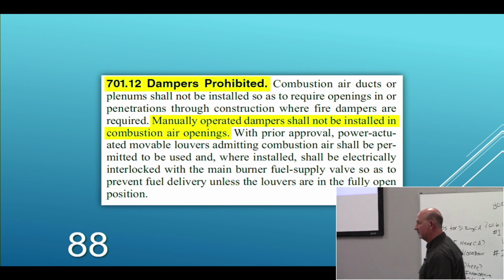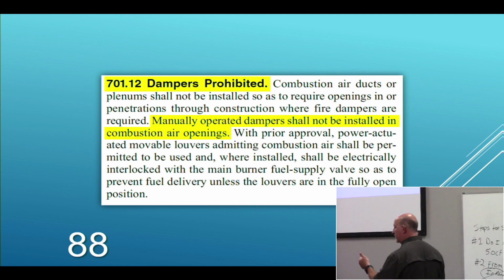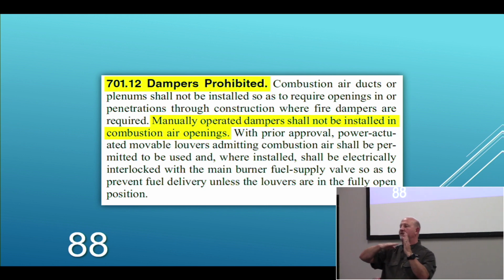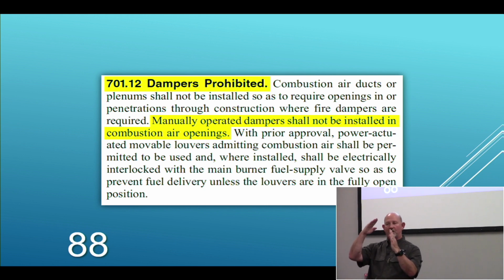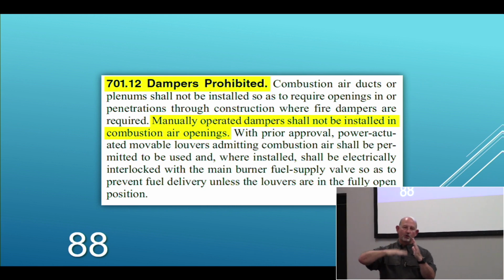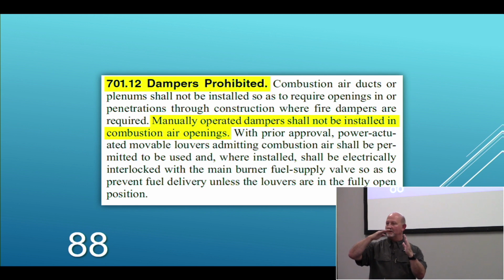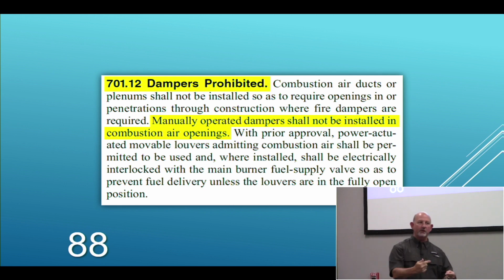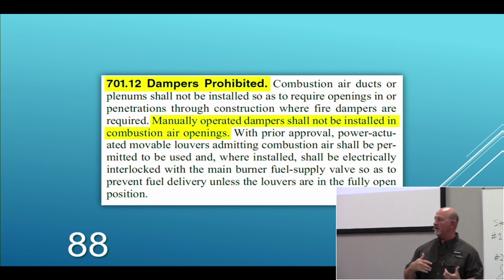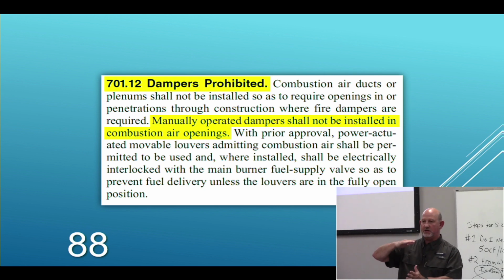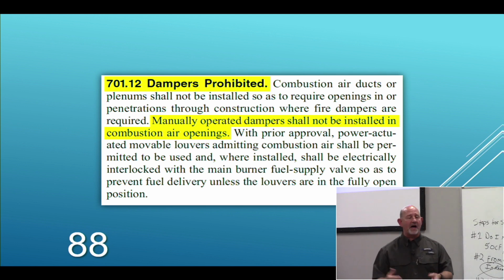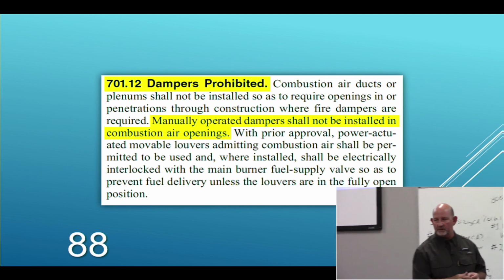Now notice what this said. You're allowed to have them, as long as they're electrically interlocked with the fuel gas valve, where the fuel will not be delivered unless the louvers are in the fully open position, right? So if those louvers start moving, we're still not giving you gas. Not until they're fully open. Then we'll give you gas to fire the unit because now the louvers are open, you're breathing air in, and then when that unit shuts down, those louvers will close again, keeping that cold air out. That would be okay. And again, that might be necessary in a really cold environment to do that.